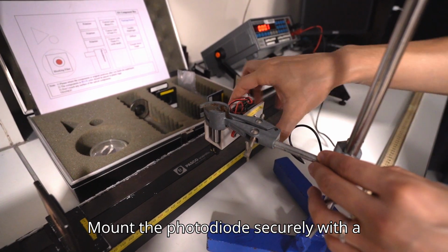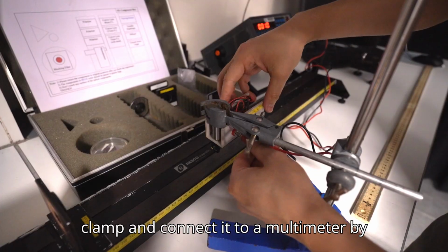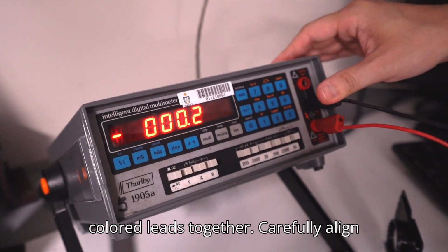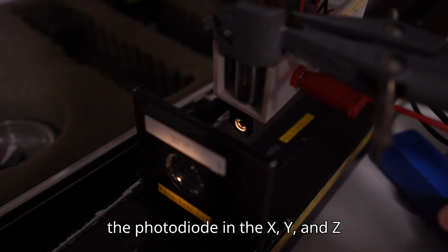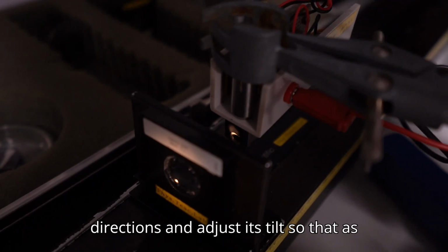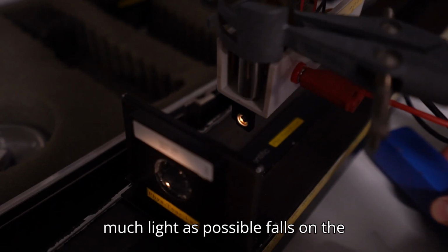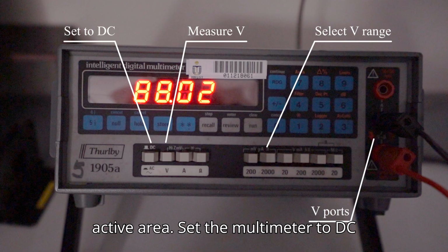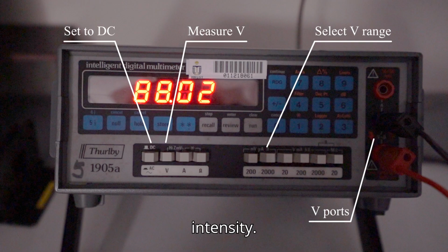Mount the photodiode securely with a clamp, and connect it to a multimeter by matching the same polarity, or the same colored leads together. Carefully align the photodiode in the X, Y, and Z directions, and adjust its tilt so that as much light as possible falls on the active area. Set the multimeter to DC mode, measure voltage, and select an appropriate range that matches the signal intensity.